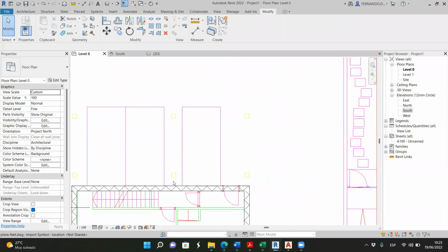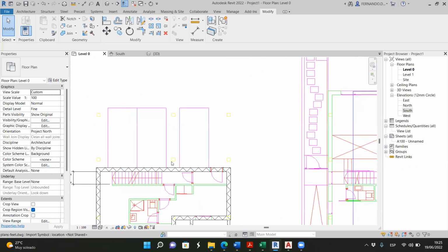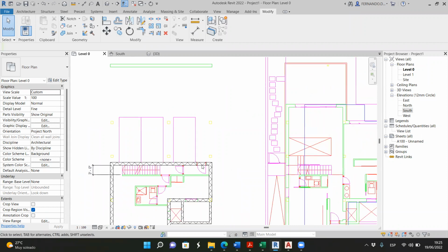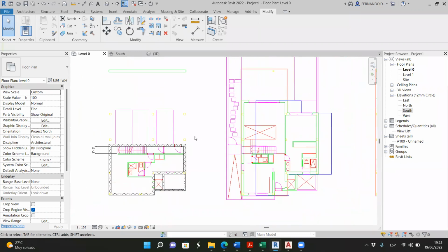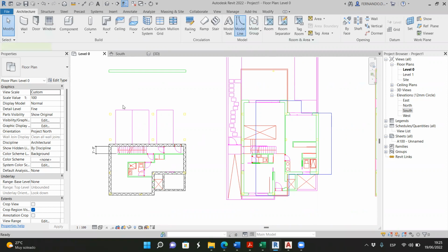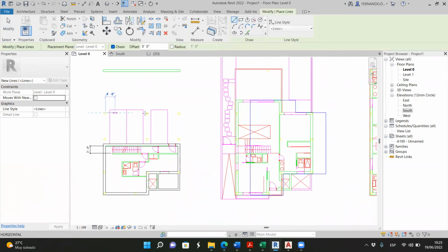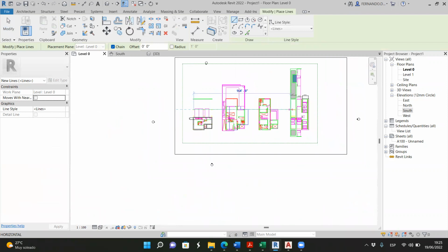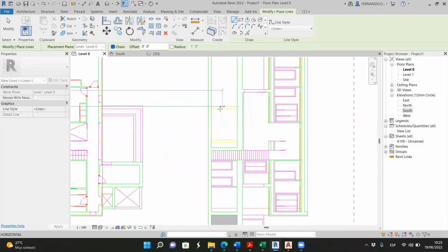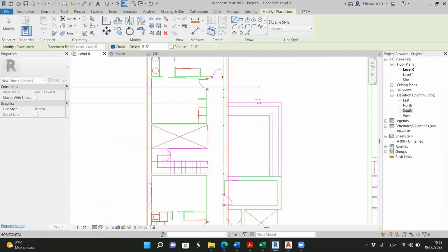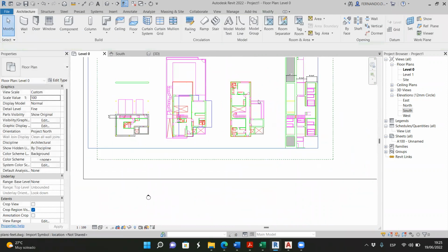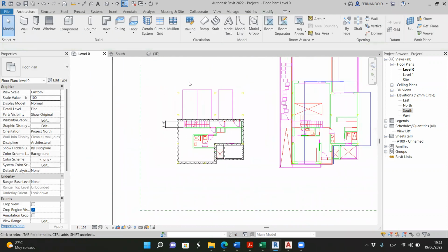And those are columns. Okay, so those columns, we have walls and columns. So these yellow squares are columns. And one of the things when we're building an actual house, we have to make sure that all columns are lined up. Okay, so if you select a line here through all these yellow lines are columns, this is the section. So we see that they are all lined up. This is very important.